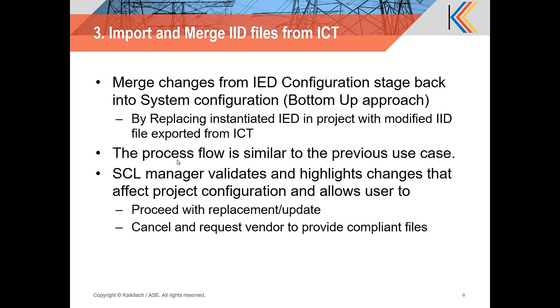And at that stage, the system integrator may need to make some changes. Typically, the changes may no longer be data model specific. It may be more to do with adding internal logic, which may involve editing or adding internal addresses. And could be anything. Essentially, this process is similar to the previous use case. From SCL Manager's point of view, there is not much of a difference. It is going to be very similar to the previous use case of updating the ICD file, except that this time the file coming in already has a lot of engineering in it. So it still performs its job in exactly the same way.